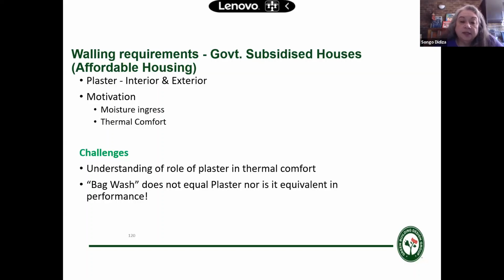In the South Cape condensation area, it was because of mold growing on the wall. If the wall is not well sealed, you get moisture ingress, and then it goes inside. The walls are damp, it's nice and warm inside, and the mold grows like a demon. When the spores open, it causes problems, especially with children, and especially with children with asthma. So it really causes respiratory problems.